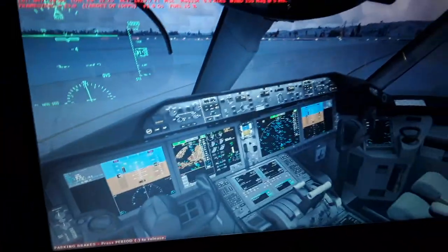So we can trim either manually using the switch here and the alternate channel of the alternate switch, or we can leave the aircraft trim itself automatically from the flight control computers like the Airbus aircraft. When we fly, it has its auto trim, the Boeing 787 and Boeing 777, to balance the aircraft in flight, in level flight in 1G, to maintain 1G, where 1G is the acceleration of gravity when the aircraft flies straight and level, or when we make left and right turns.